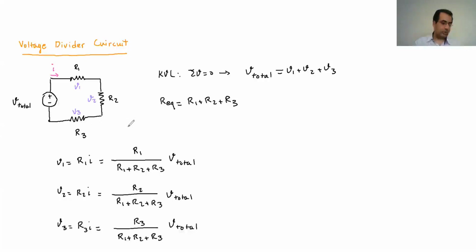And the whole point, again, one more time, is that you can find the voltage without needing to find the I. You can directly find the voltage in each of the resistors that are in series without calculating the I. So the next one, here the voltage, as I said before, is divided between R1, R2, and R3.